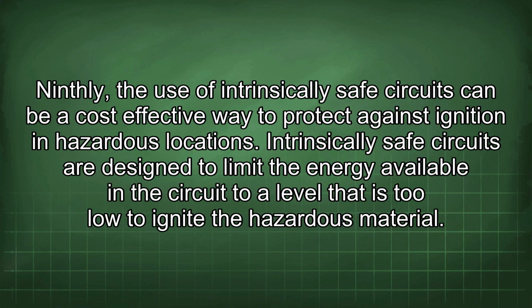Ninthly, the use of intrinsically safe circuits can be a cost-effective way to protect against ignition in hazardous locations. Intrinsically safe circuits are designed to limit the energy available in the circuit to a level that is too low to ignite the hazardous material.